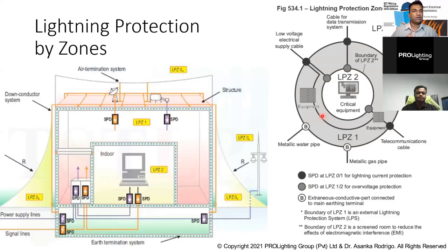When you look at the first one, it is the overvoltage protection, or what we call transient overvoltage protection. As I said earlier, when you look at the distribution board, the main equipment were the overcurrent protective device and the earth fault protective device. But now with the regulation changes, they are specifying not only those two, but we have to have arc fault detection as well as transient overvoltage protection.